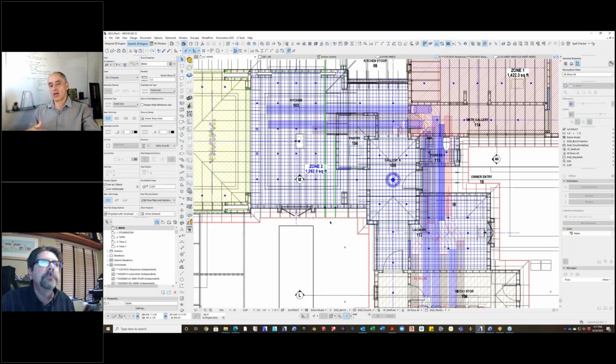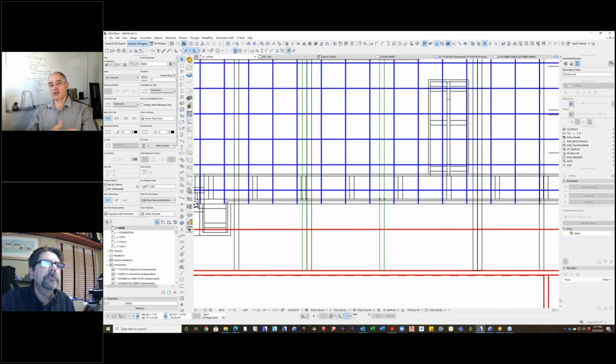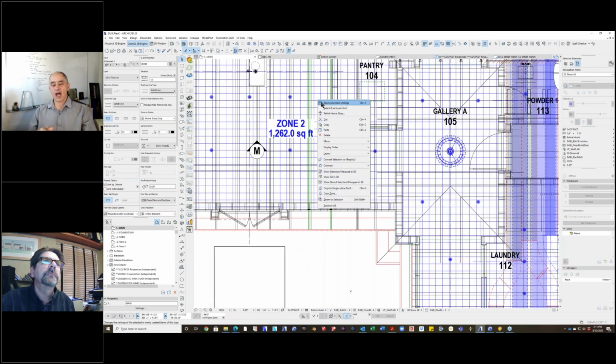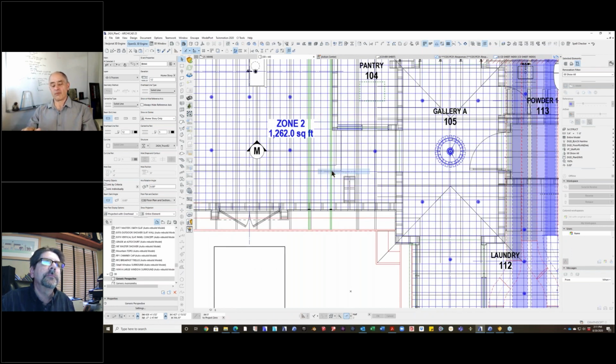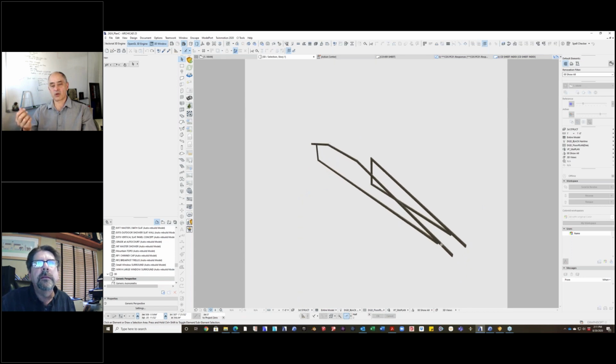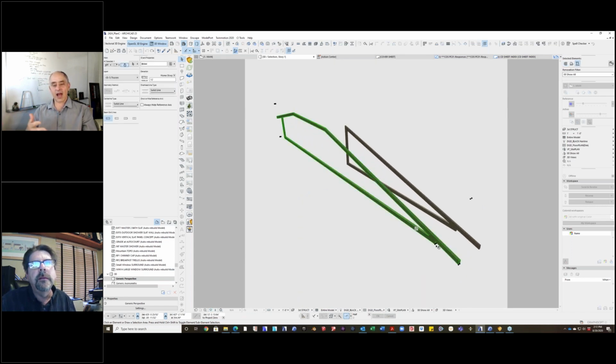In this case, the shape is actually the profile, that whole long, complex series of angled pieces. And instead of it running many feet or meters along, it's running just the thickness of the framing. So a 2x6, it would go 5.5 inches deep.